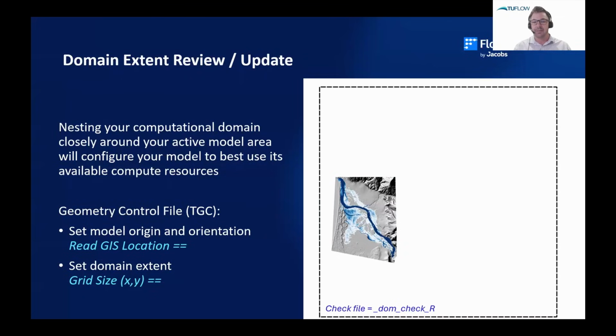In TUFLOW, I highly recommend after you build your first model to load your domain check file. There's the name of it down at the bottom of the white polygon there, dom check r. Load that file in and it'll bring up a polygon. That's the black dotted line that I have on the screen here surrounding my model area.